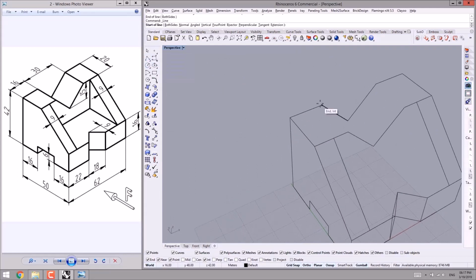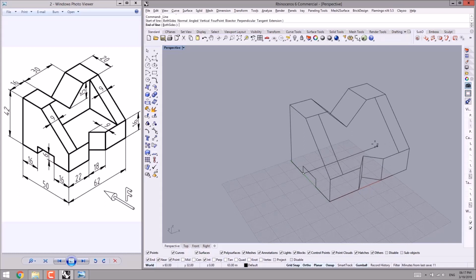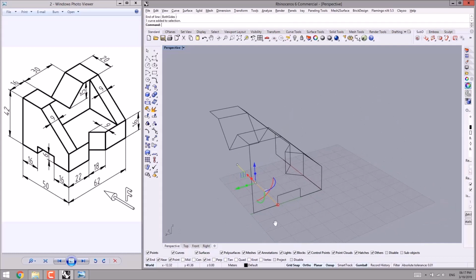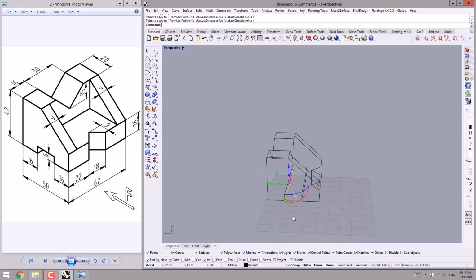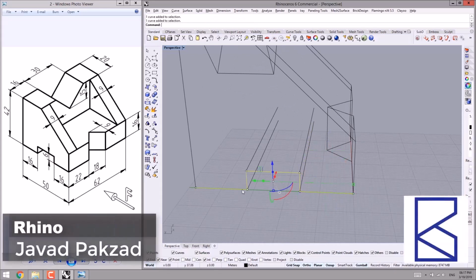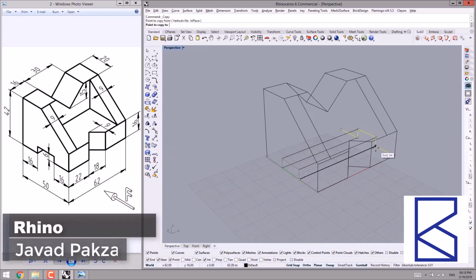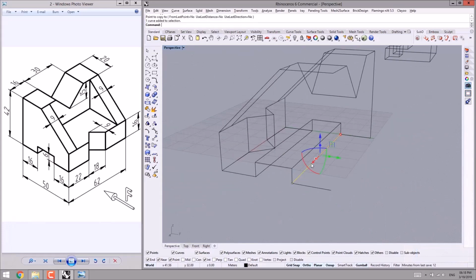Again by picking single line command to sketch the intersections and corners like this. After that, the line for the bottom part is 62 units. Check this out. Then I can select the previous line for making copies like this way and then place them at the four corners. Right now I select the polyline here, I click on copy command, then I duplicate it to place it at the other side.